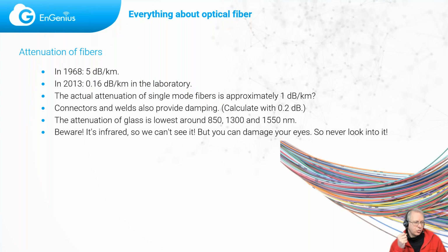It's very important to remember that it's infrared. It's not a wavelength that we can see. So looking into a fiber to see if it lights up is not a good idea. It can and probably will damage your eyes, just like looking into the sun is not a good idea.